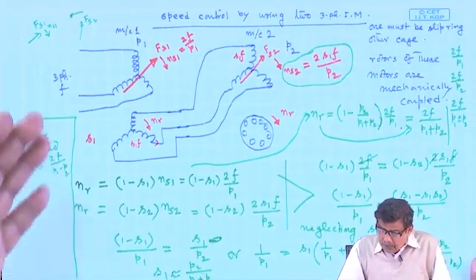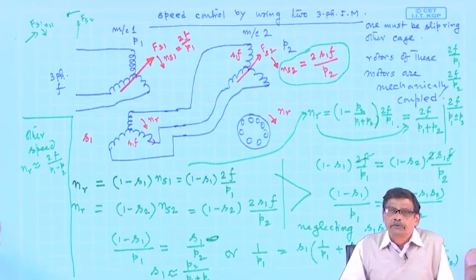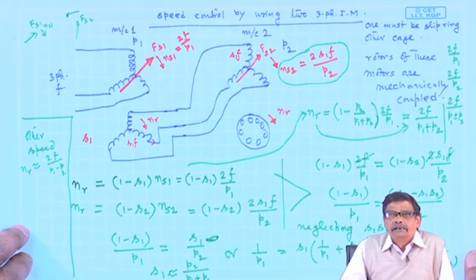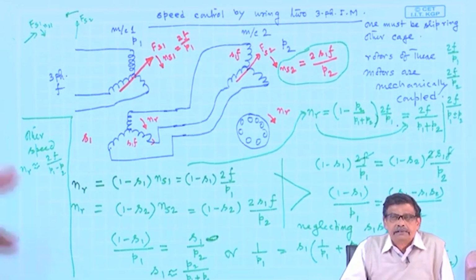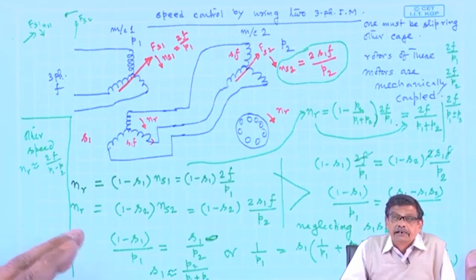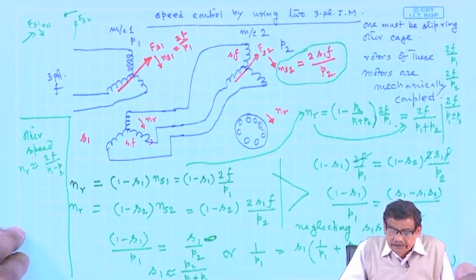See, this is how people fought with how to control the speed of an induction motor and make it a very good drive, making it a real competitor of DC motors. That is, with the advent of rectifier and inverter sets, those can be very nicely done.